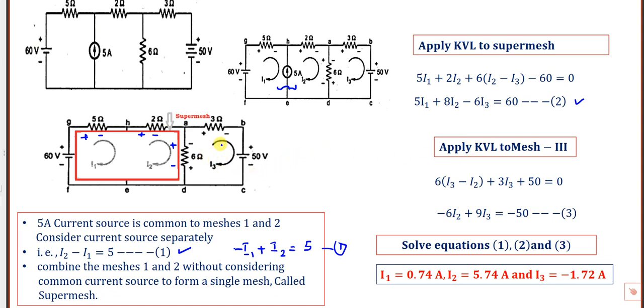Three equations are required. Now apply KVL for mesh 3. Plus minus, plus minus. You can start from any one; here it is started from 6. You can start from 3 also, or from 50 also. It is the same equation, but one complete circle you have to write. While writing KVL for mesh 3, you have to assume I3 is greater. So 6 into I3 minus I2, because two currents are flowing; it is not at the edge, it is between two meshes.